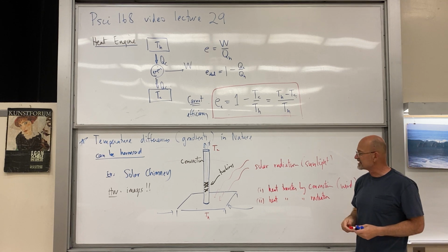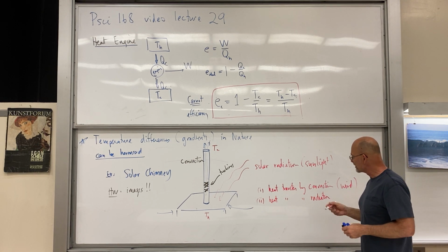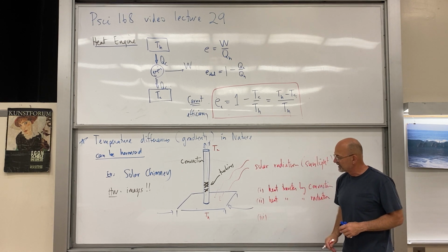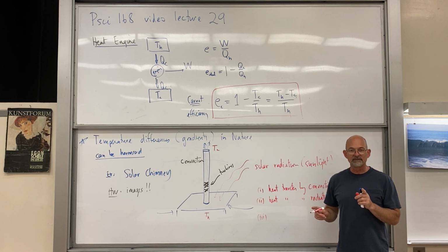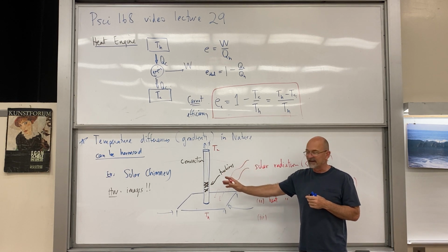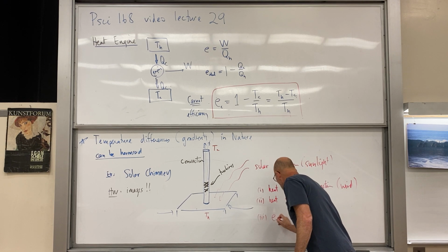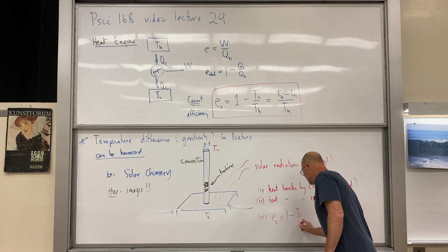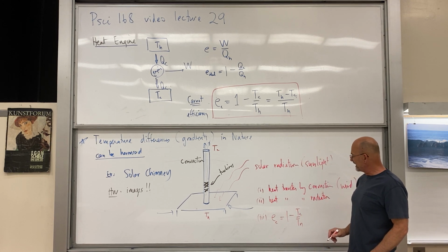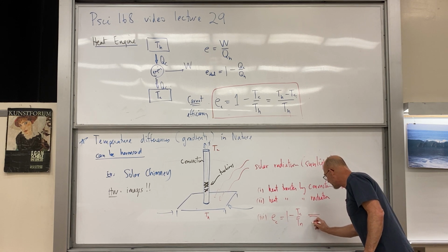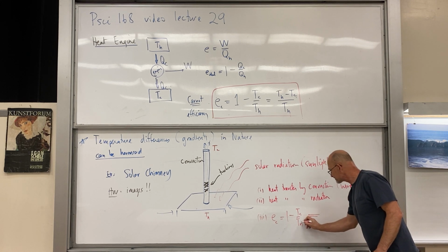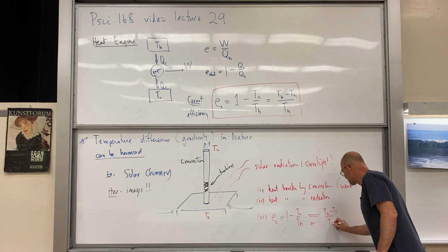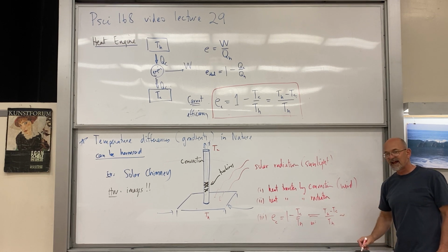So what is the efficiency of this machine? So maximum efficiency, that's why we're studying this. So before you even build this thing, you can know the maximum amount of energy that you're going to be able to get. Okay. So the maximum efficiency is 1 minus Tc over Th, and I'm just going to make up some numbers, as an example. So I do the Th minus Tc version over Th.